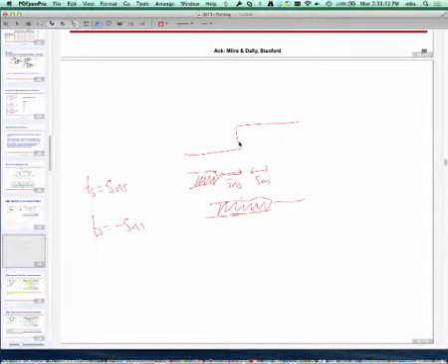Hold time, same story. Normally, hold time is positive. So normally, we would say that the data can begin to change after some time. So this would be my hold time. Okay. But if hold time is negative, let's consider a flip-flop where setup time is minus 5 nanoseconds and hold time is 10 nanoseconds.